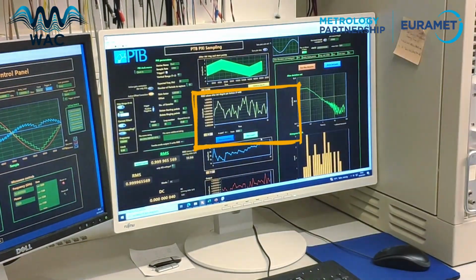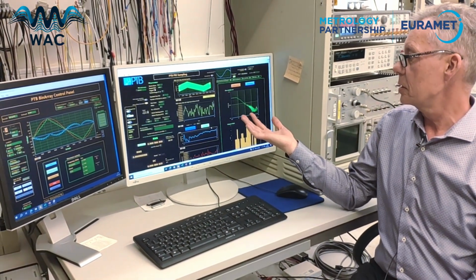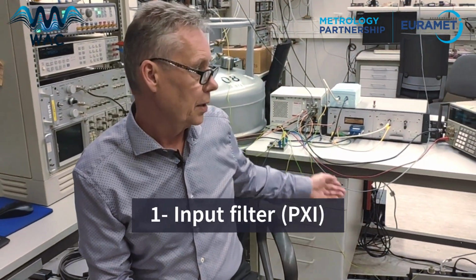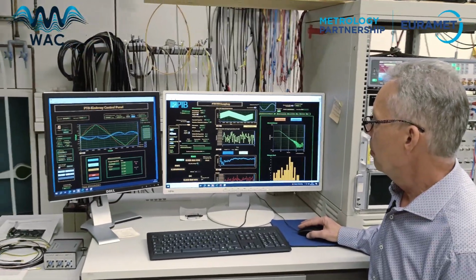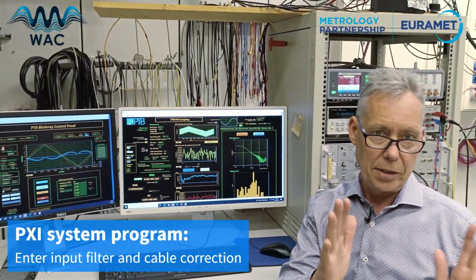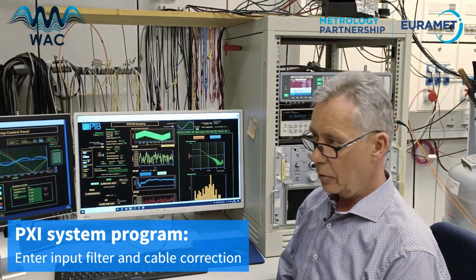Now we are recording the RMS value of this, and what is important to mention here is that because we are going to a very high frequency, we have to consider the input filter and the cable correction. To consider the input filter correction, I have to click on this button here, which means all our measured data are immediately corrected by this filter function of the PXI, and I have the proper reading.